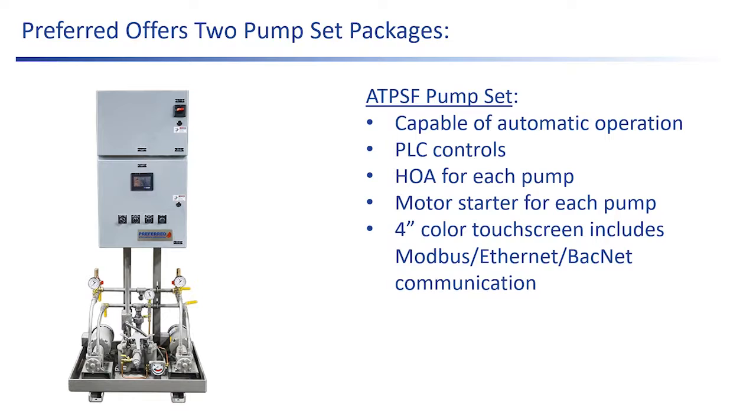It's the same lead lag logic that we use on our gensets. And it's a little bit of an automatic lead lag. So in case something fails with one pump, it'll automatically switch over to the other pump. And if neither pump proves flow, then we're going to go into alarm and we're going to de-energize both pumps so that we don't burn up the pumps.